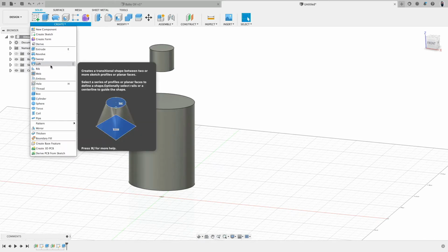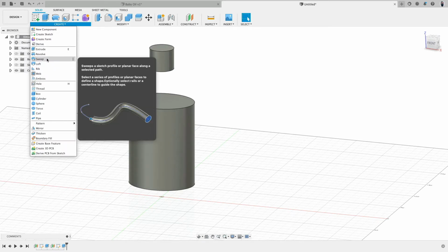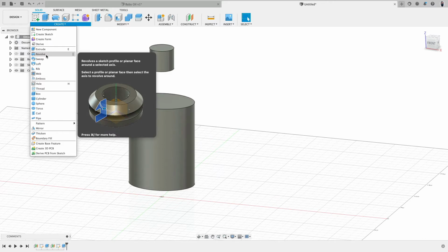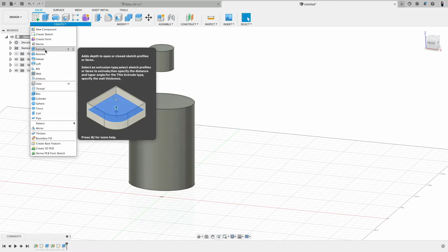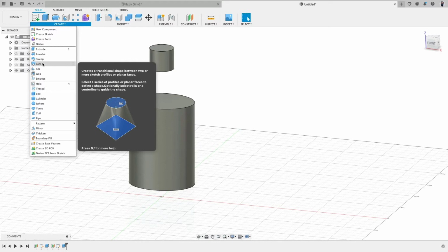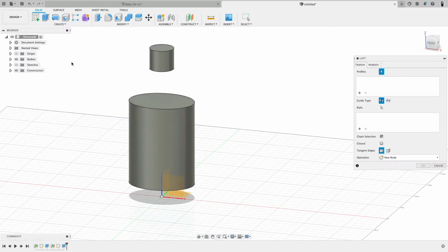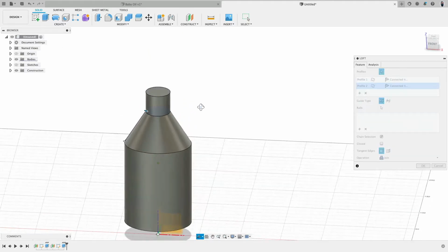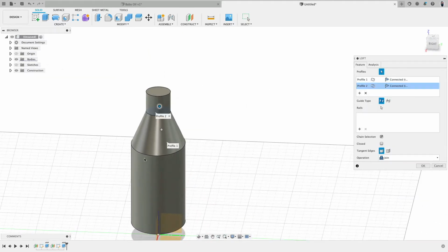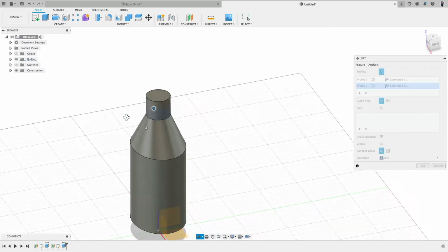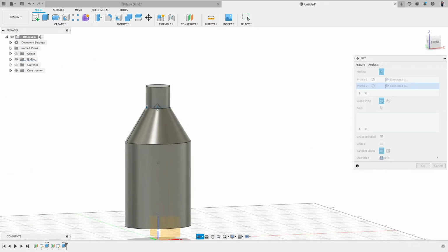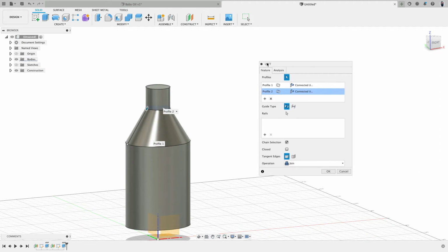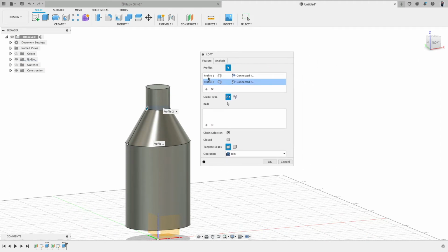Welcome to Loft. So far we learned that revolve rotates, extrude moves it in one direction, and loft, think about it as a blend. So click loft, click this one, click this one, and then we get this transition. You see it goes from an ellipse to a circle. Wonderful tool. Let's take a look at the features here.